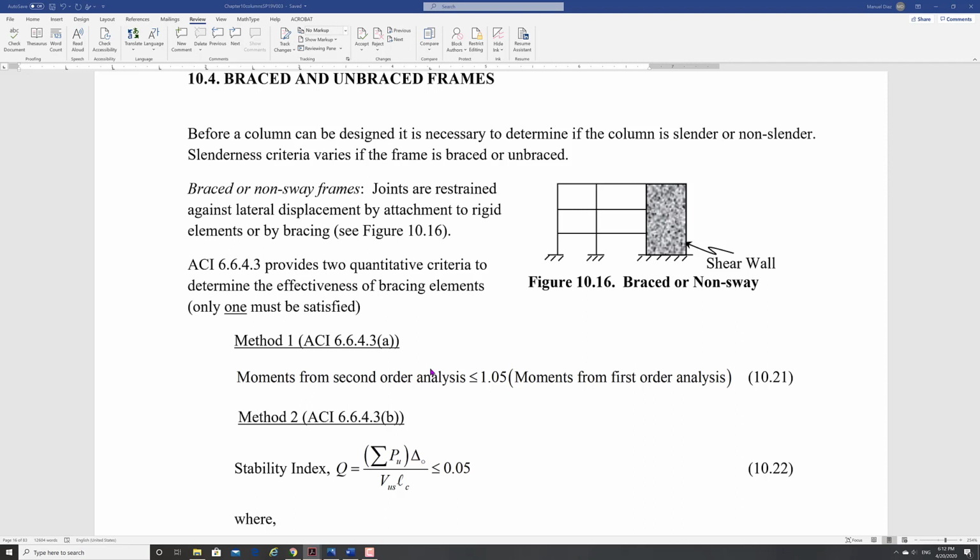So there are different levels of analysis depending on what you're trying to do. So we run it for this one, we use this method. Then we look for a software that offers this option. Then we run it again, right? And we compare the results. And if we pass the 5% difference, then we got a case that now sways rather than non-sway.